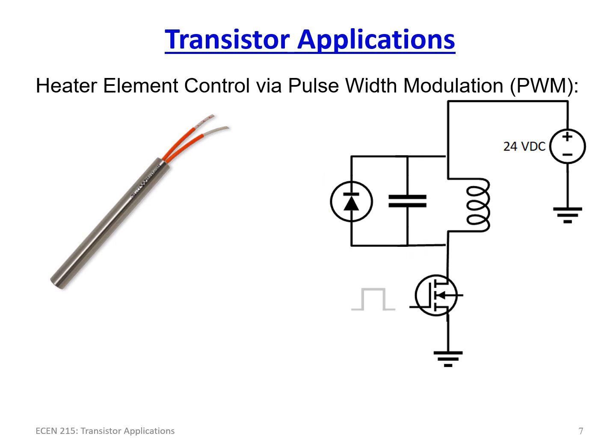Notice again, we simply have one NMOS transistor here. In this condition, you could also use a PNP or an NPN BJT transistor, but typically today we use NMOS, and we have our gate here. Again, this is the drain and the source, and all we have to do is again provide a signal that is 0 volts up to about probably 3.3 volts or 5 volts.